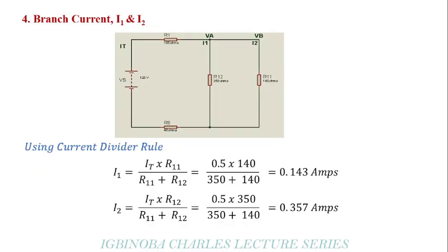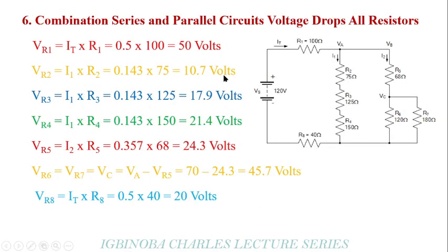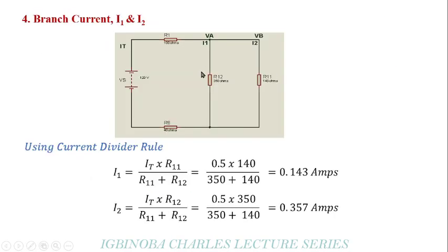All we need to do is get the equivalent circuit to represent that, which is this. Now, applying the current divider rule to calculate the current flowing through this point, we use this resistor times the total current divided by this plus this. Then to calculate the current flowing through this point, we use this resistor times the total current flowing in the circuit divided by this plus this.